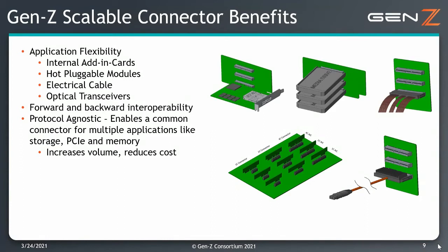And the other added benefit that we've talked about in previous webinars around the GenZ Scalable connector is that it supports PCIe 5.0, 100 gigabit Ethernet, and provides a pathway to 112 gigabit per second PAM4 channel performance.